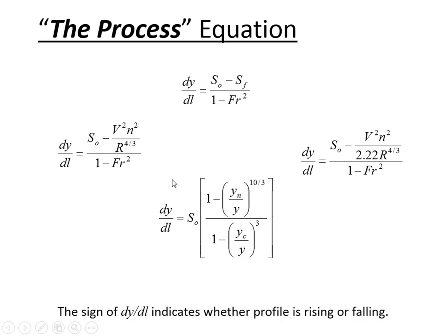Well, this is the simplification for a wide channel. This is always valid, and these are always valid. So I maybe should give you the warning on this slide too, that this is the wide channel version of it. But most natural streams are wide. Engineered streams, drainage canals, sometimes aren't, but a natural earthen channel is ordinarily going to be wide. It would be an exception for it not to be.